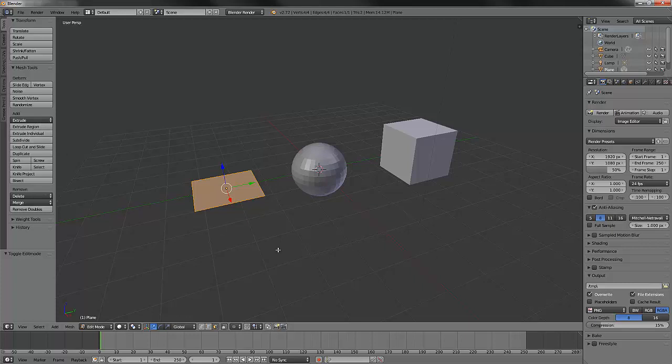We can also access our extrude tool through two hotkeys, because of course we can, and preferably that's how we'll always do it. Those hotkeys are, as you might suspect, E, and the additional one is Alt-E. Now, if we hit E for an extrusion, that will access regional extrusion immediately. If we use Alt-E, that will give us access to Blender's Extrude menu. Let's look at some forms of extrusion.